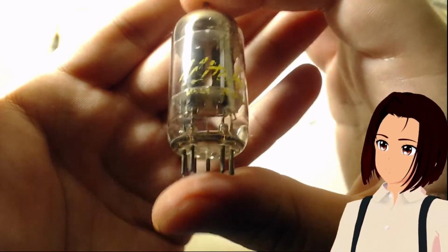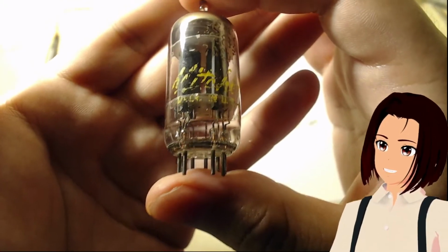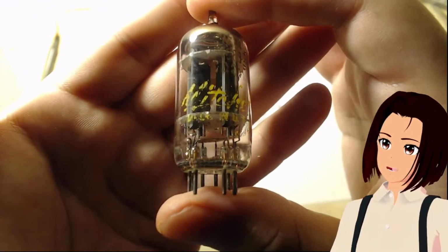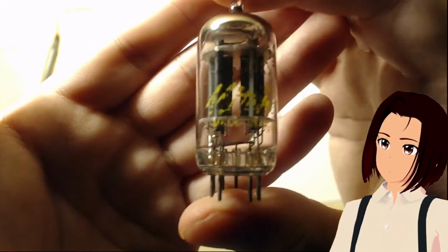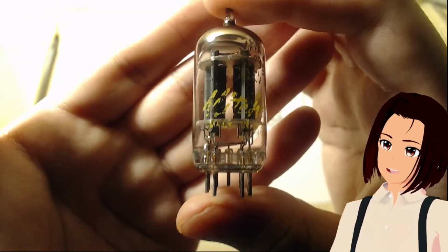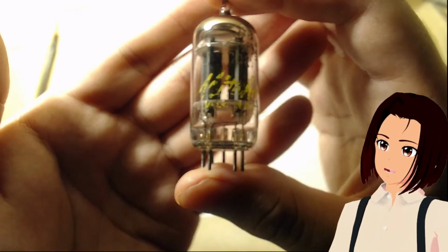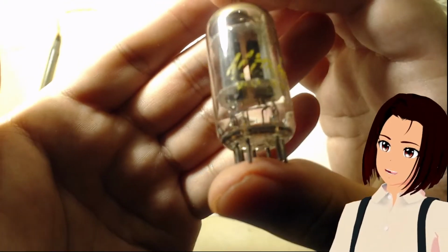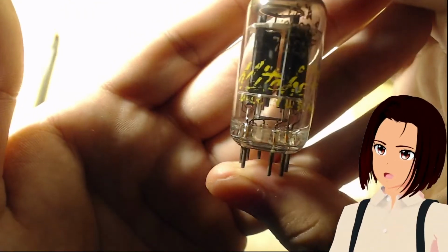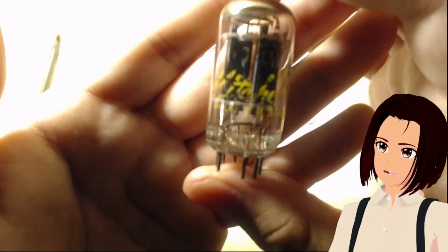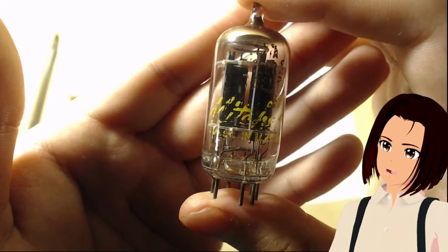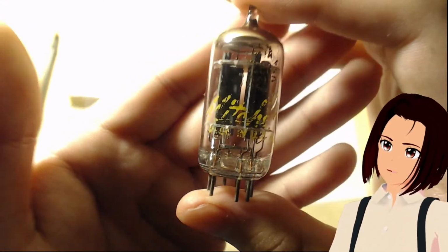Now, the tetrodes, since their amplification factor isn't as high as a pentode or beam tetrode, the voltage used on these things isn't as high. Therefore, these things actually last quite a bit longer, possibly 10,000 operating hours. This one is probably halfway through. I don't know if you can see the logo, but this is actually a USA made tube. I think there are only 4 factories left in the world that make tubes.